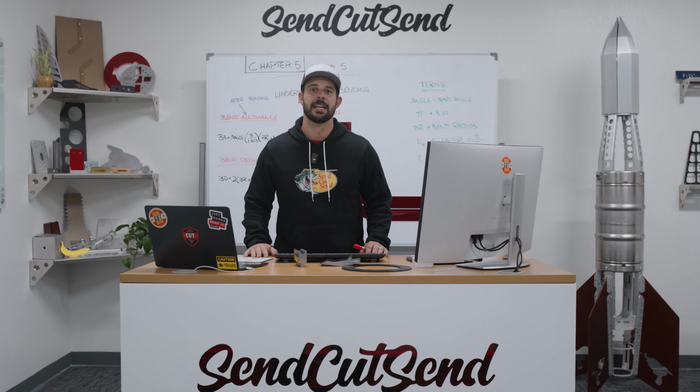Now, I promised you that we were using those key terms again. Here they are. So we're going to go over angle. Pi is a new one. Now this is just a constant from a mathematical standpoint. We're going to use 3.14 in all of our calculations. We have bend radius, our K factor, and again this is our midline thickness divided by our original material thickness. And then lastly our overall material thickness.